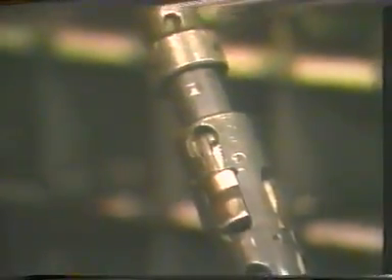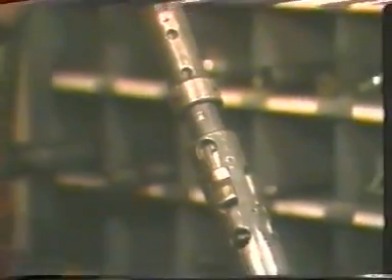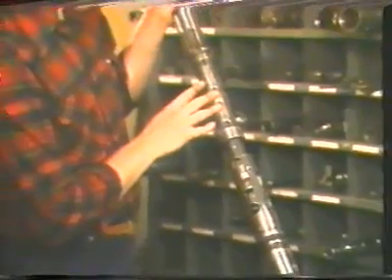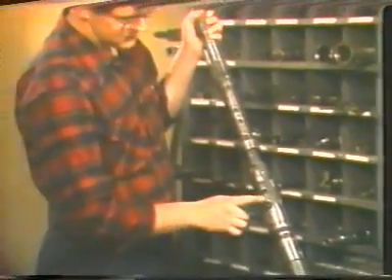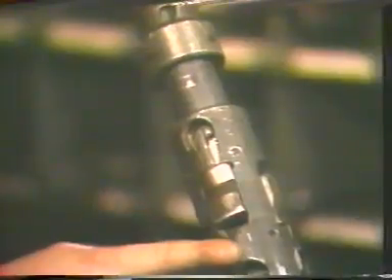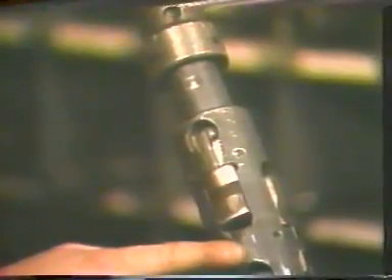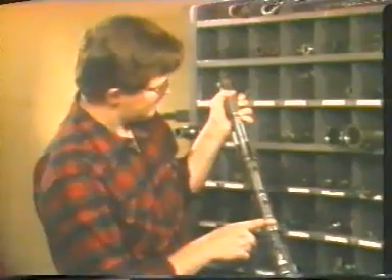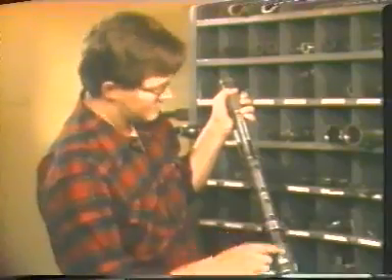Another running tool designed to run the S-lock is called the Model E running tool. Once pinned to the E running tool, the S-lock is run in the tubing with wire line. The lock passes through the tubing and nipples because the locks are held retracted by a plunger in the running tool. Once the nipple in which the lock is to be set is passed, the tools are pulled back to